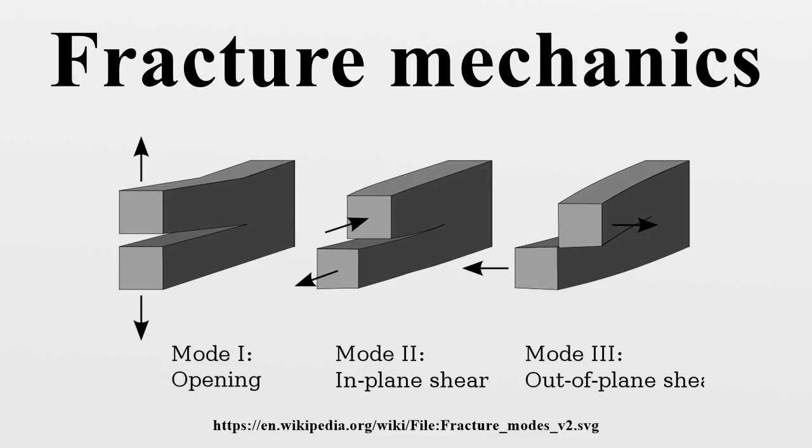loading conditions. Next, Irwin adopted the additional assumption that the size and shape of the energy dissipation zone remains approximately constant during brittle fracture. This assumption suggests that the energy needed to create a unit fracture surface is a constant that depends only on the material. This new material property was given the name fracture toughness and designated GIC. Today, it is the critical stress intensity factor KIC, found in the plane strain condition, which is accepted as the defining property in linear elastic fracture mechanics.